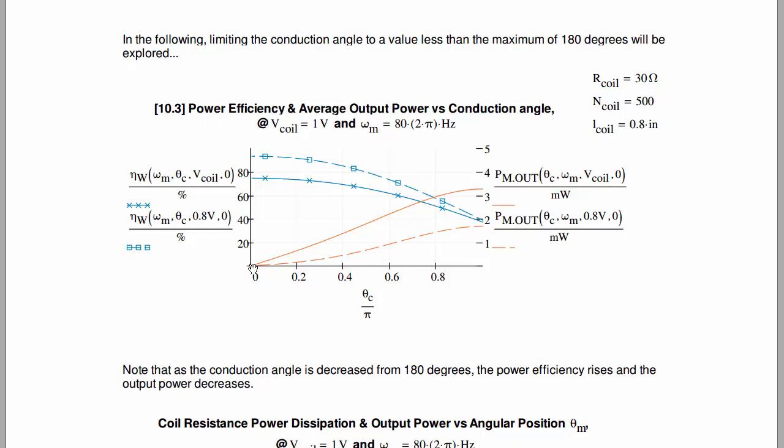But before we have moved too far away in angular position from where that coil operates with maximum efficiency, we disconnect it and we connect the next coil, the next phase, as it approaches its optimum efficiency point. And when we put a number of those together over a full rotational cycle of the rotor, we can dramatically increase the net power efficiency of the motor.